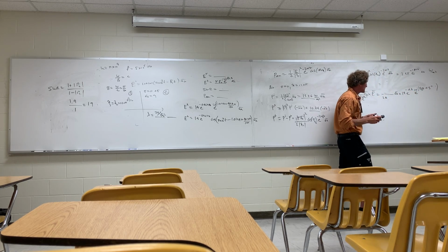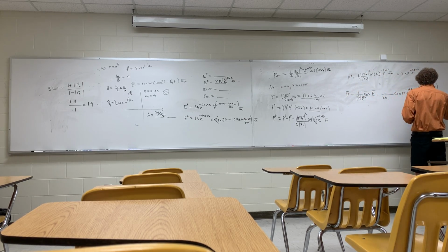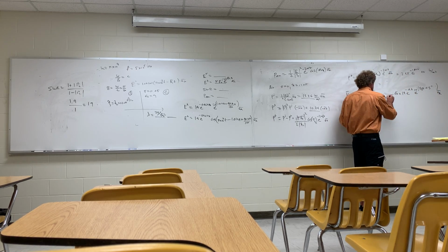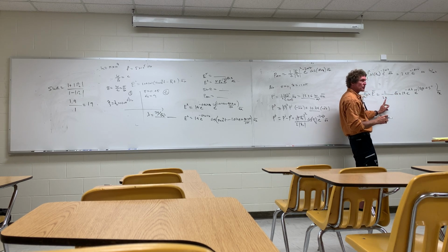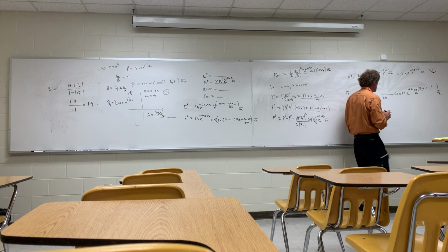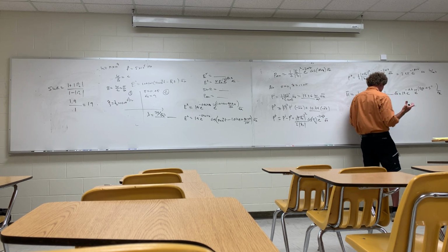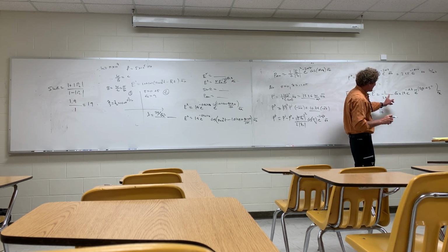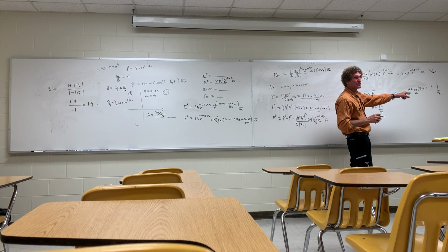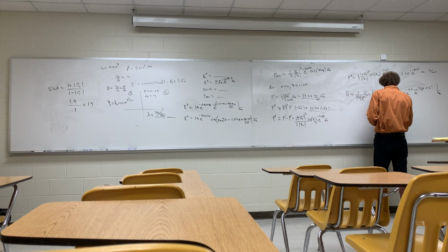Now, when I do this, and this is actually in the x direction, right? Now when I take a look at this, I have 14 over 28. It's the magnitude of the H field in region 2, correct, class? So the H field in region 2 has a magnitude of 14 over 28, or 1/2. Right? Now I have AZ crossed AX, which is AY, correct? So this is in the AY direction.